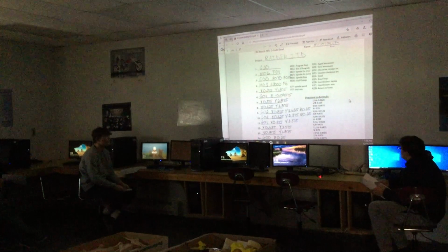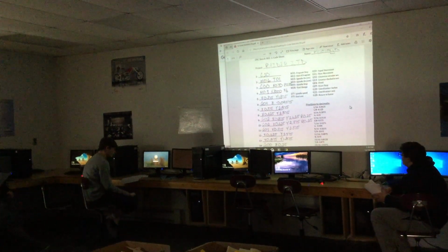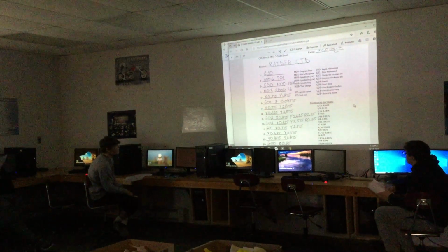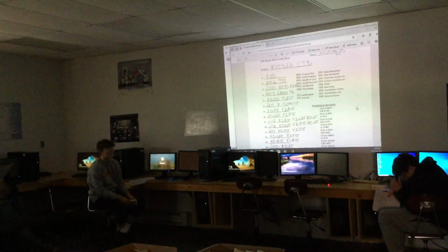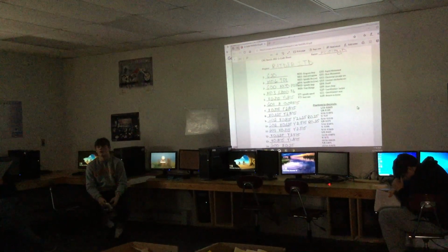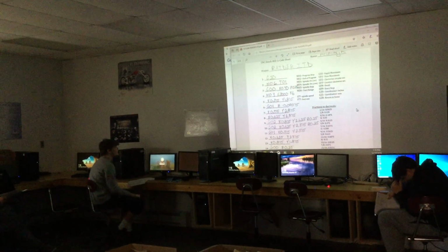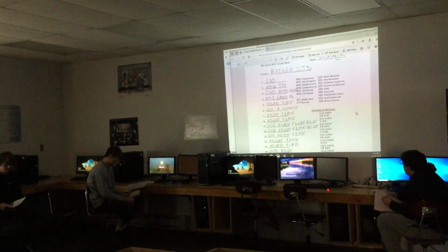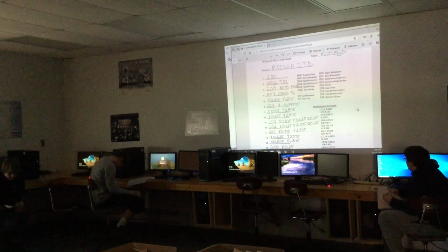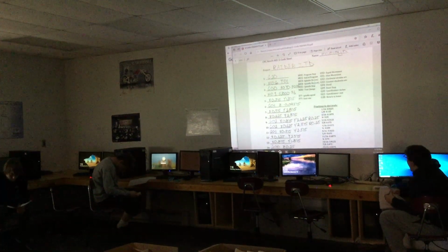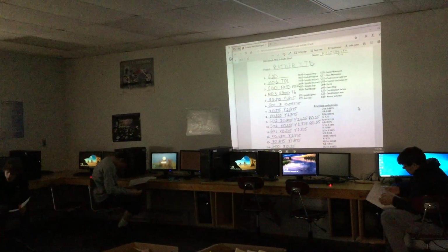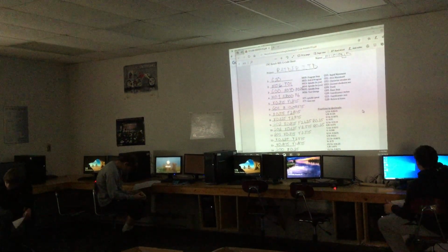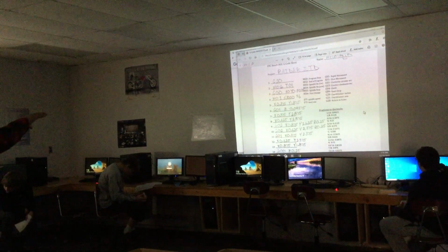When you have a fraction, you have a calculator and you know it's 3/32. How do you find the decimal? 3 divided by 32, and it gives you 0.09375. Now, why did I have to put a negative? So it goes down. Because when I set the machine up, I set everything up so the bottom left corner of your board is X0, Y0, Z0, right on top. So anything negative you put down is going to put that cutter down in there. So at step 6, it goes down.